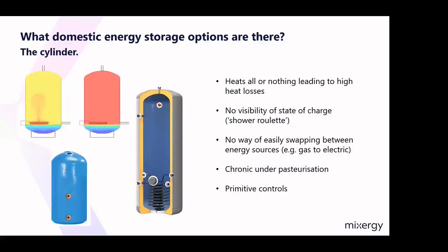So, storing energy in a traditional hot water cylinder. Traditional hot water cylinders have been used in many different ways since the early 1800s. The first unvented cylinder was developed by Sir Thomas Hawksley in 1861, and the design has relatively stayed stable since then. Today, a traditional cylinder comes in three forms: direct, which utilises an electric immersion heater; indirect, with a coil at the bottom of the cylinder, which usually has a boiler as a heat source, and is fed from a header tank, usually located in a loft space; and unvented, pressurised.